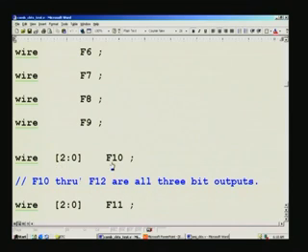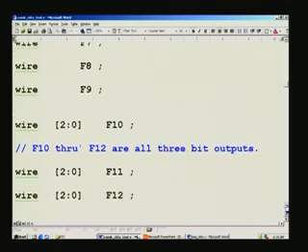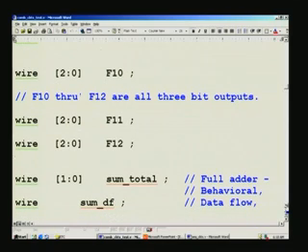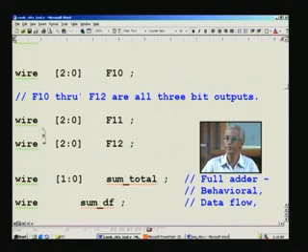And we had some other outputs which are 3 bits in width, and therefore it is mentioned as 2 to 0 here, and all the outputs, or combinational outputs, are wire. So, it is very simple. In the test bench all the inputs are declared as reg, all outputs are declared as wire, right. Note the difference between a design file and this.